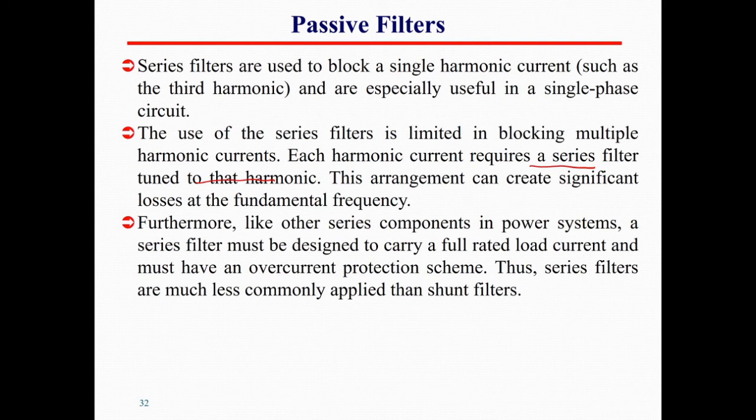Like other series components in a power system, a series filter must be designed to carry the full rated load current and must have overcurrent protection. Therefore, series filters are less commonly applied compared with shunt filters.